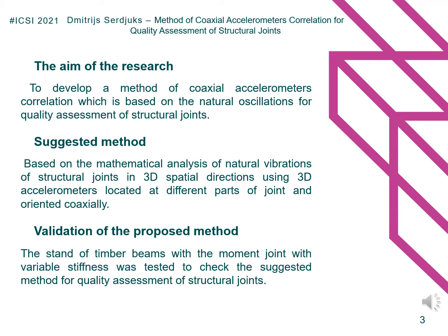The aim of the current study is to develop a method which is based on the natural oscillations for quality assessment of the structural joints. The method should be based on the mathematical analysis of natural vibrations of structural joints in 3D spatial directions using 3D accelerometers located at different parts of the joint and oriented coaxially.